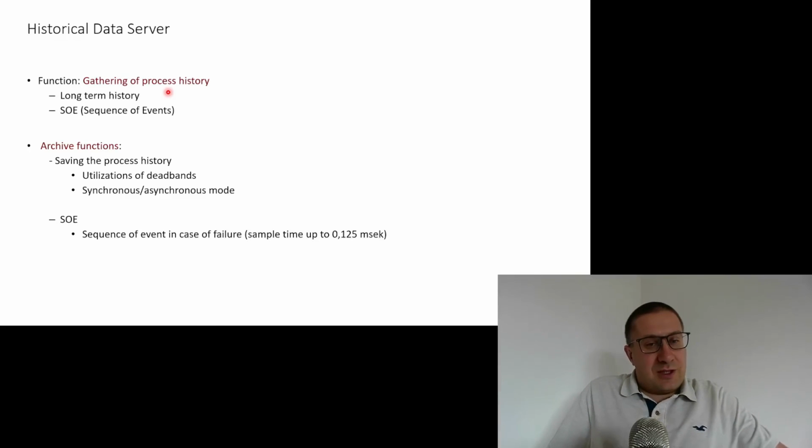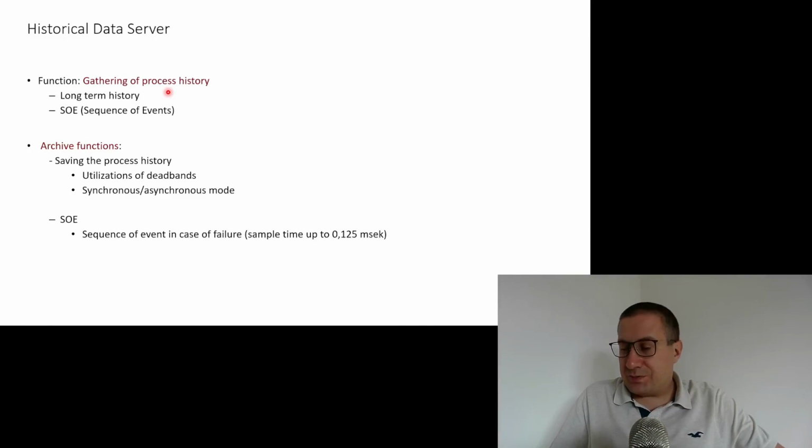One more important issue. There are many ways of storing the historical values. One of the popular ways is the asynchronous mode with the utilization of deadbands.